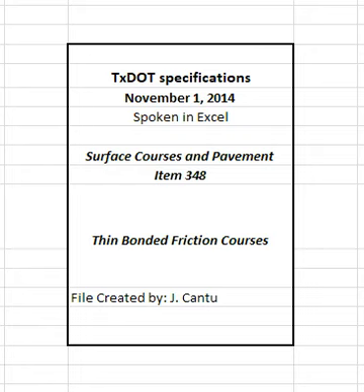Request the department test the stockpile for specification compliance, and, once approved, do not add material to the stockpile unless otherwise approved. Provide aggregate from non-listed sources only when tested by the engineer and approved before use. Allow 30 calendar days for the engineer to sample, test, and report results for non-listed sources.